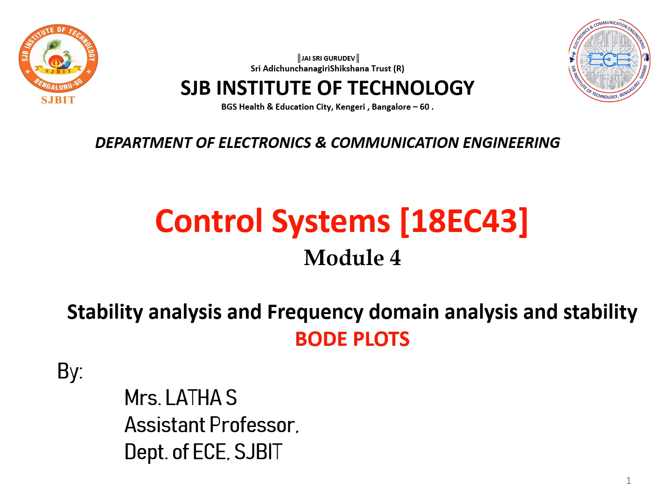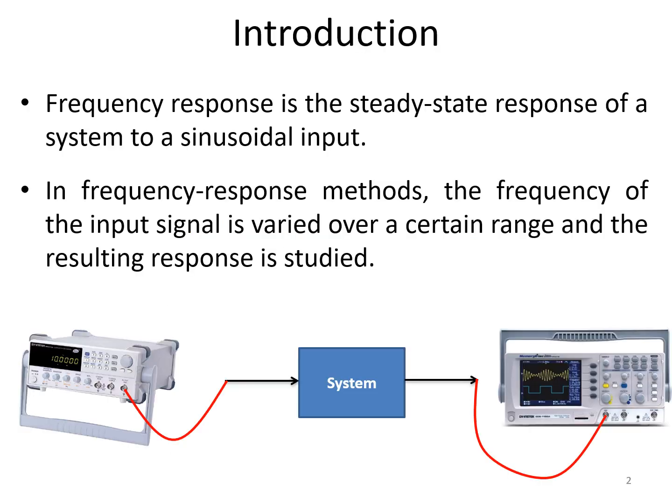We'll be discussing another stability analysis technique in the frequency domain named Bode plots. So coming to the introduction, frequency response is considered as the steady state response of a system to a sinusoidal input. So here, as you can see, we are giving a sinusoidal input to a system. The response, whatever I am going to get out of this input, is termed as the steady state response.